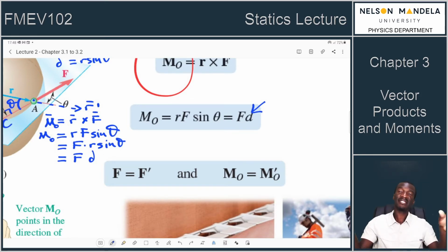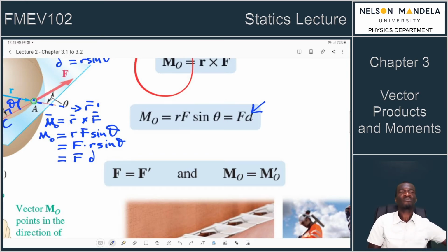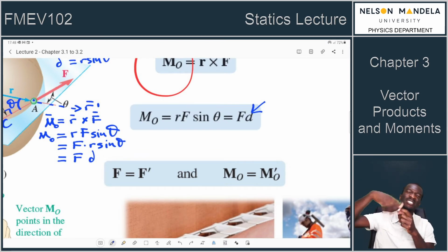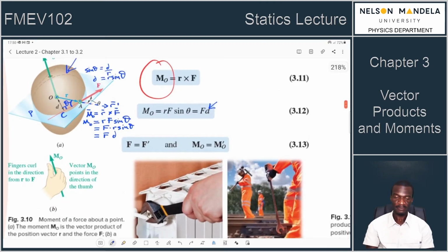If you look at all the forces acting, there is the object there that you want to place onto the flat. It's got some weight, right? The crane is at the road, and this boom is into the building. So there's a weight that rotates this crane. All you want is to now figure out, okay, since we have this weight and this crane has its own mass, there's a reaction from the ground, the boom has some strings or some hydraulic system that is either pulling or pushing this object, then how do we find an equivalent force system so that we just counteract that? If we just find one equivalent force and we counteract it, the system is in equilibrium. Then our crane won't topple. So that's the idea.